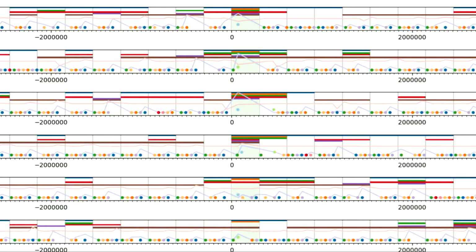And the colored dots are the response messages color-coded by type of response message from the controller. So you can see that when we are spamming out invalid cards, there's a clear pattern. And then when we're outputting a valid card, you can clearly see that there's a big gap, right, while it's busy thinking. That's because the controller is doing a sort of two-pass thing. It's checking, is the facility code even valid? If it is, then there's more to do. But if there isn't, I can just instantly say, no, go away.